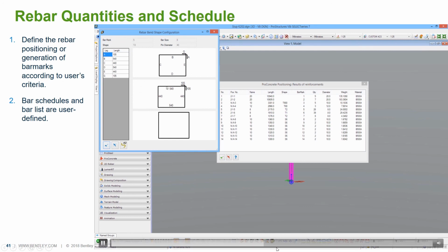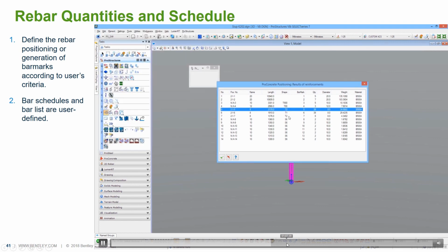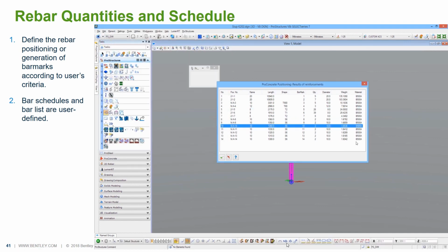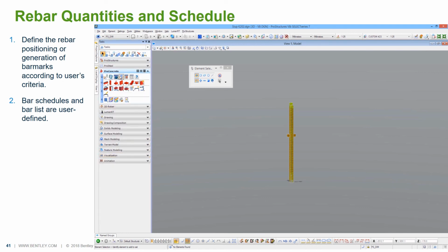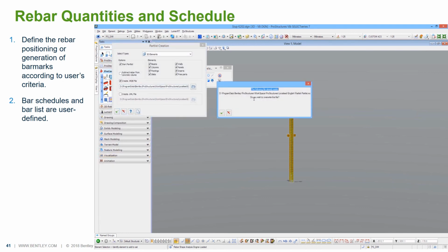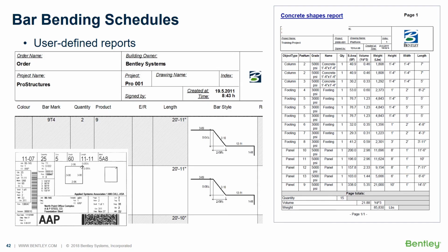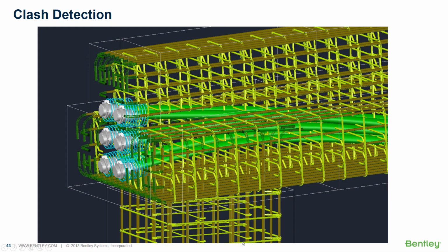And it can recognize any type of bar or any type of bending. So that will be the ending process of your whole modeling that started again with a line, then you developed the bridge, then the quantities, the geometric reports, the creation of plan sheets, and now the full detailing of your bridge. Because at the end of the day, this is what you want to generate: a list of quantities, as I said, a bar bending schedule, all part of the 3D model. So you can just generate this in great detail.